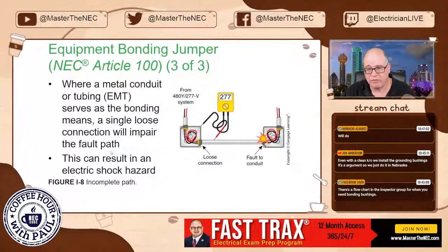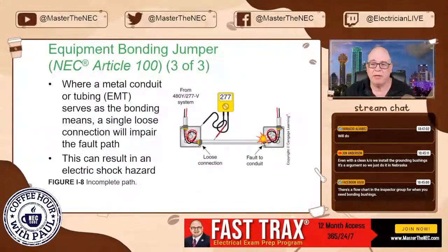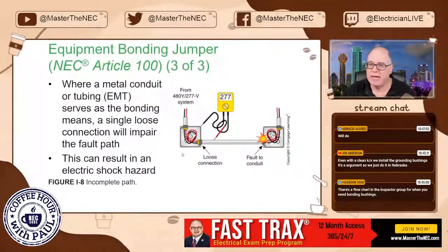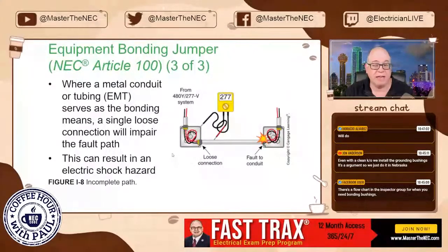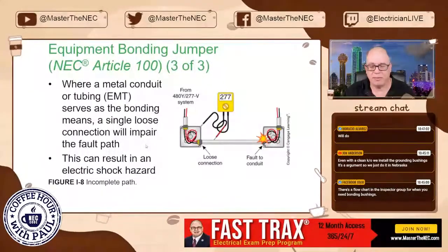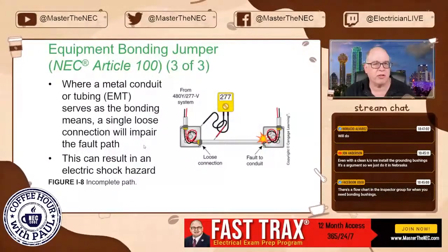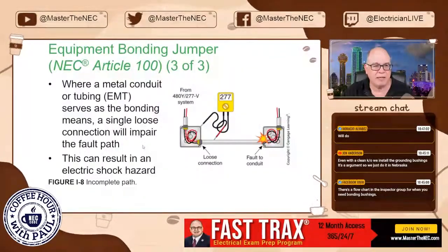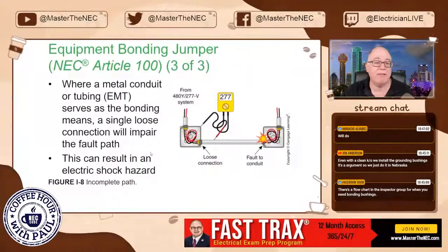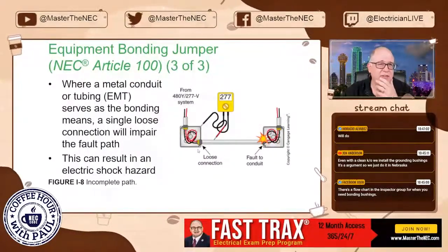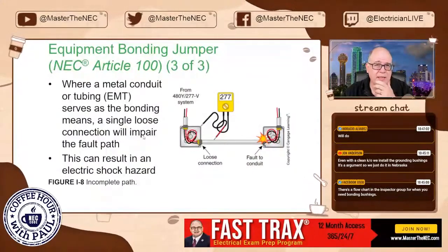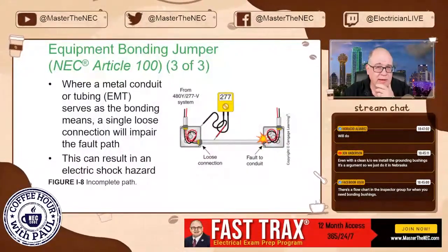So this can create a hazard. That's why, please, if you're the supervisor, make sure that you harp on your guys and gals to make proper terminations, okay? Properly secure the couplings, properly secure the connectors. Set screws have to be done, okay? That type of thing. And believe it or not, did you know that even the set screws on a coupling have to be torqued? I bet you didn't know that.